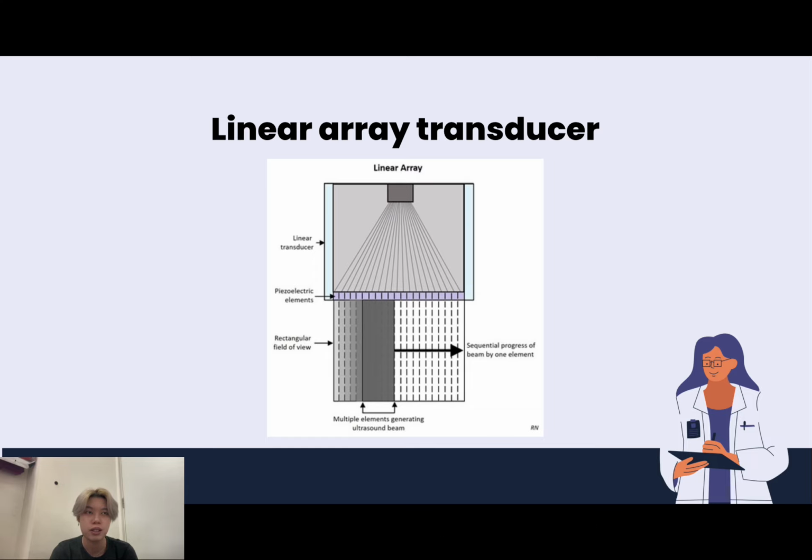the transducer. Ultrasound echoes that are received are understood to correspond to the beam's core element. The ultrasonic beam is created when a small group of about 20 nearby elements fire simultaneously. The number of active elements determines the synthetic aperture, or effective transducer width, created by the simultaneous activation. In the receive mode, signals from the majority of the transducer elements are acquired in order to detect echoes. When one or two transducer elements are displaced, another group of transducer elements is fired to do a subsequent A-line